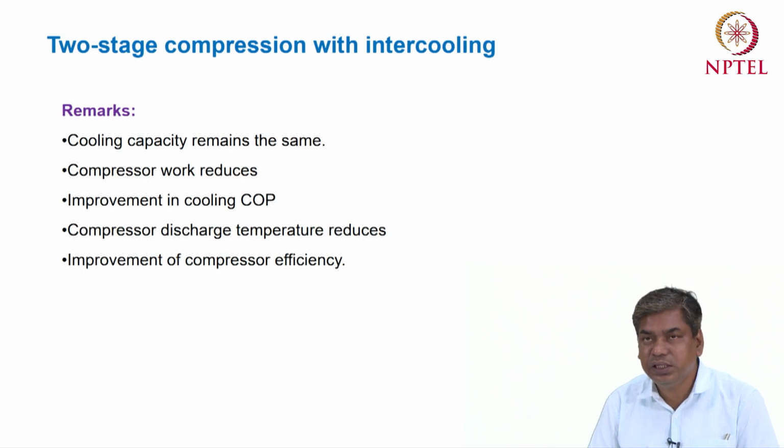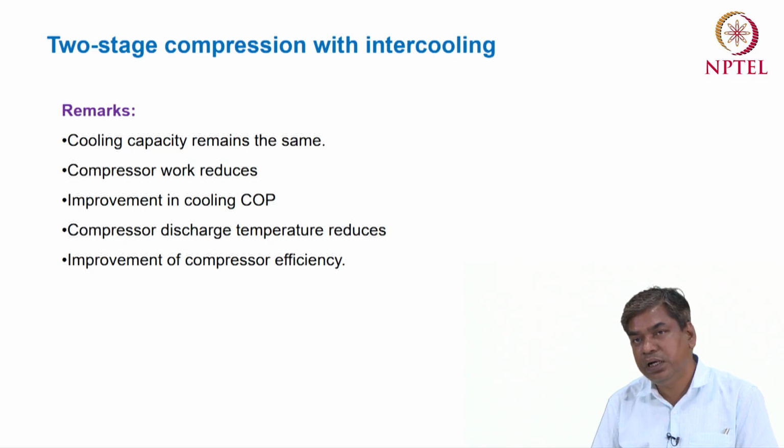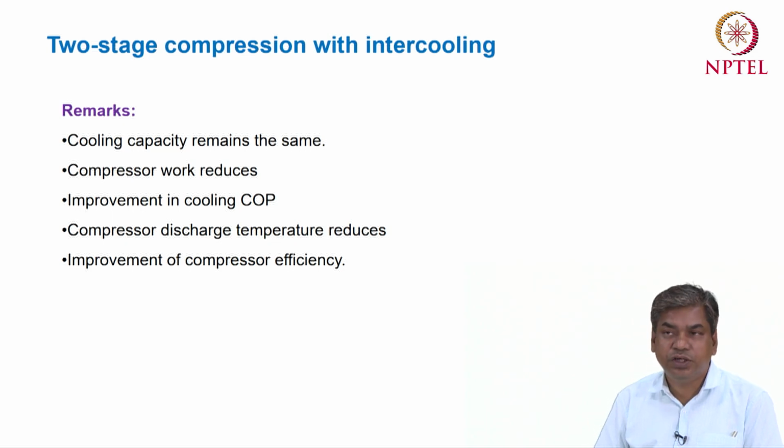Basically, the compressor isentropic efficiency depends on the pressure ratio of the compressor. A higher pressure ratio will give a lower value of the isentropic efficiency.